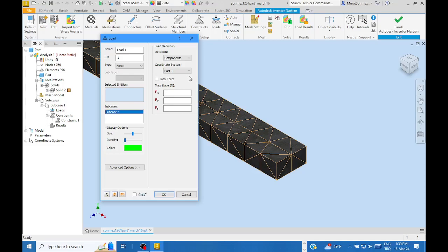In classical usage, we have a flip-flop facility. If the force is compression, although it is tension type, click on the flip-flop button. In Nastran, there is no flip-flop button to change the direction sense of the force. The method is this: see the ellipse at the corner with the X, Y, Z axes. The X-axis has its positive sense in this direction.